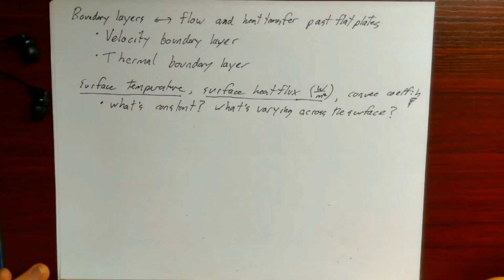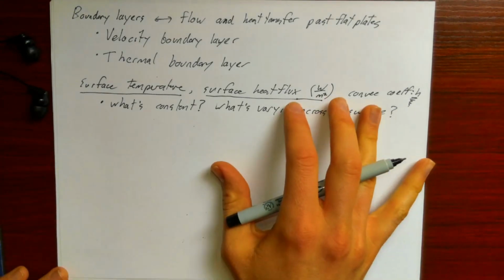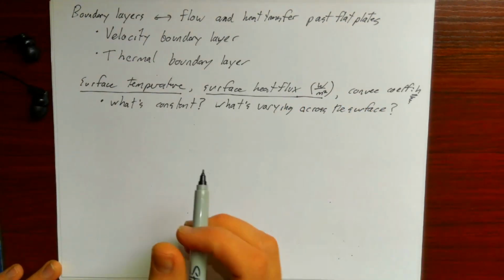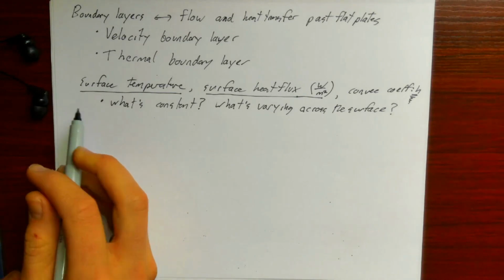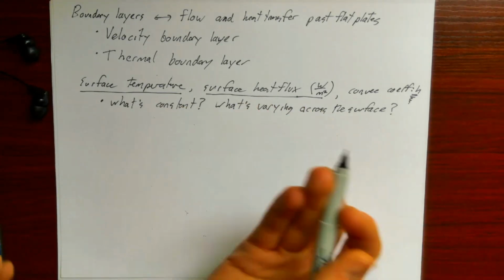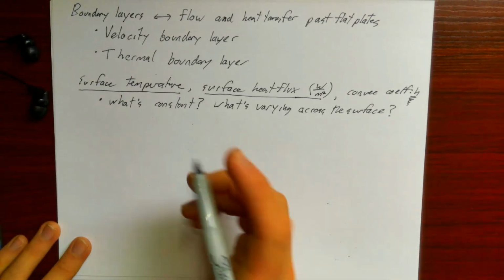Basically, the whole plate kind of has this developing boundary layer. So there's not really a fully developed plate. Basically, the flow is always developing across a plate. So with that in mind, entrance length is essentially always important. There's not really a well-defined entrance length at all. The whole plate is the entrance length.